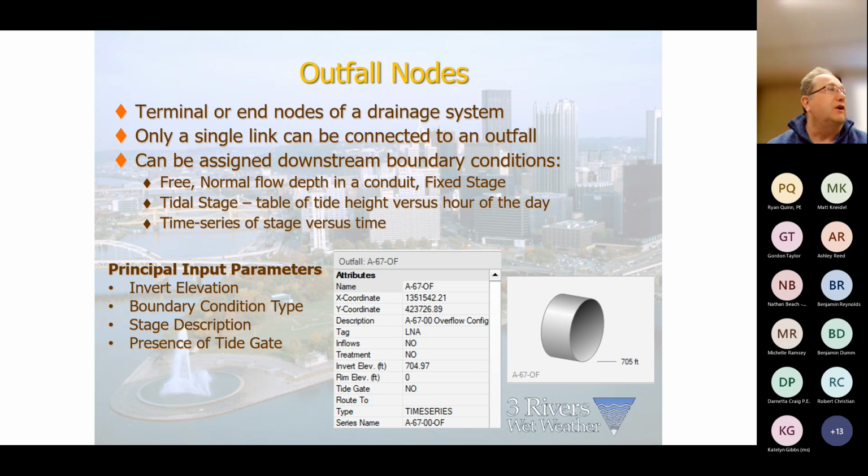There are some boundary conditions in for some of the upstream tribs, but not all of them. So that's something to think through. If you know of an outfall that is impacted by the response within the stream system or river system, and there's not a boundary condition, that may be something we might want to look at adding. The question is, is there data available to do that? That's one of the challenges when you get in the tribs, there's not always available data to do that.